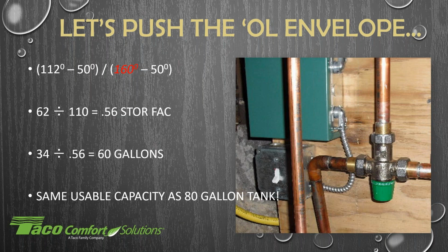Nagesh has got a question and just says, are the tankless water heaters controlled the same way? I would say no, but you want to speak to that? I think where he's going is the aquastat setting. They do have a temperature setting on them, but you typically don't use mixing valves with tankless heaters.